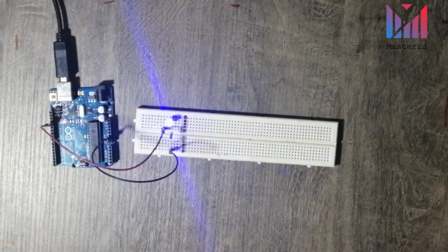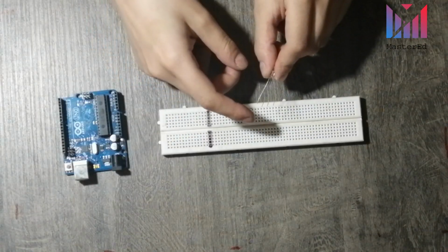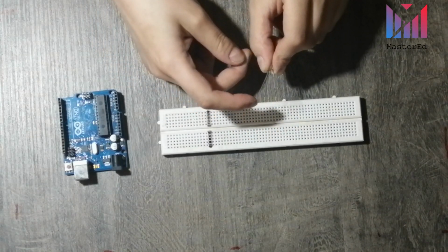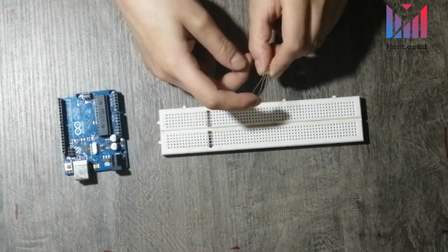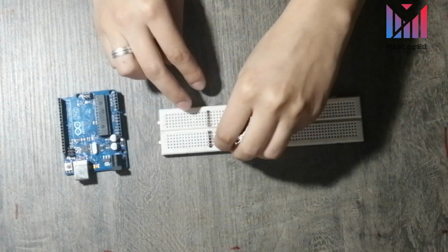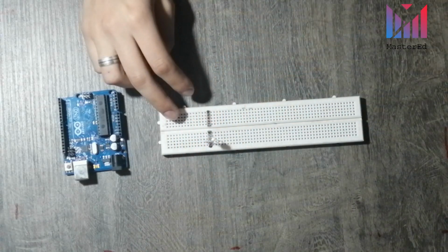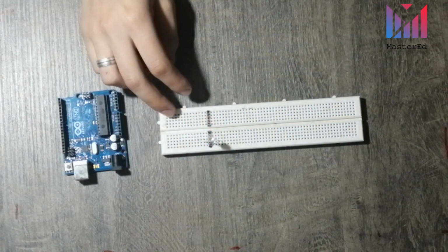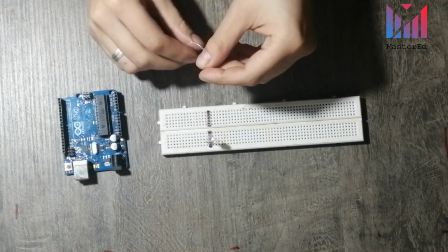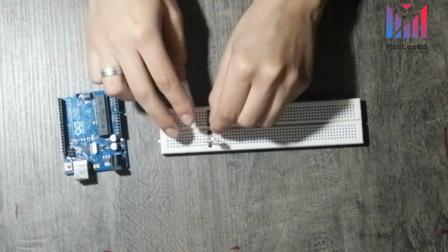Welcome to the club. Now, let's do an example which you can show to your mom with RGB lights. It has 4 legs indicating red, green, blue, and the negative. In this case, the longest leg is the negative one. So we should put it right here. Then we should use the same resistor and connect it to the negative pin, like this.